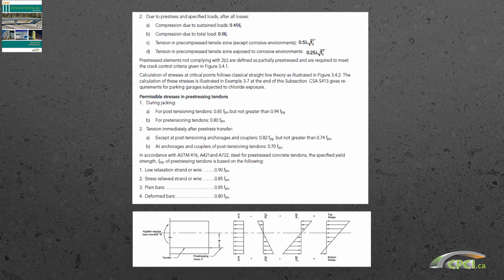We assume in this analysis that the strain is linear, so basically we can simply add up the cases of load as if we are adding up linear to linear to linear, P over A. This is here the pre-stressing diagram, the moment diagram. This is the diagram due to moment, and these are the final one. We add them up as we go, case by case.